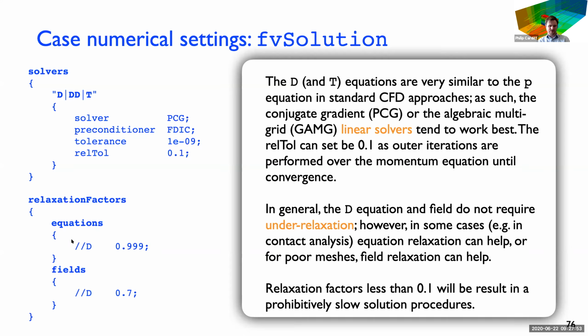Normally you don't need any relaxation. Maybe if your mesh is bad or you have large deformations or something like that, applying a bit of displacement relaxation tends to help. And very rarely, you might need equation relaxation, like in contact analysis, two things contacting. Sometimes if one's kind of floating in space and it's a steady state case, you might need a small amount of equation relaxation.